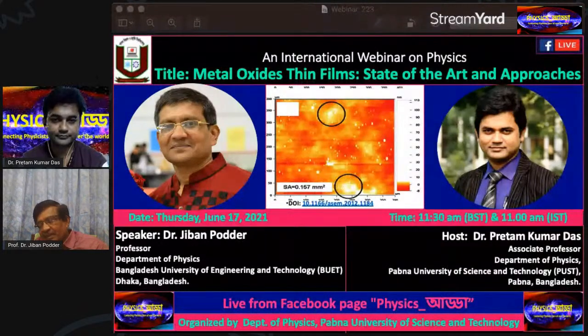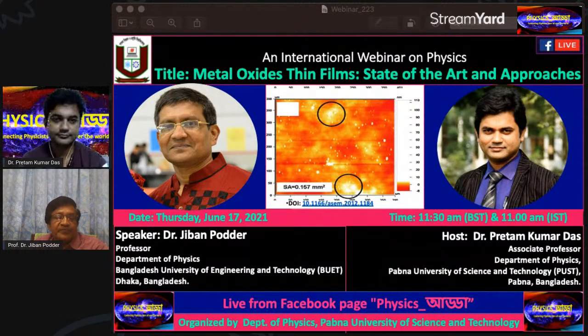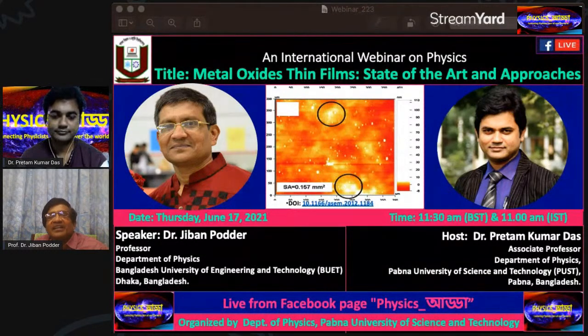Actually, this magnetic behavior we can study only if we use cobalt, nickel, iron, that type of material. So magnetic behavior is another property we need if we use magnetic components. But especially for nickel oxide, copper oxide or manganese oxide, for sensor applications, we don't need the magnetic characterizations. For sensing applications, we are using tin oxides, right? Widely used zinc oxides. These are all non-magnetic. So the magnetic properties are needed only if you want to make switching devices, right? Diluted magnetic semiconductor switching, magnetic switches and other performance, for that we need the magnetic studies.